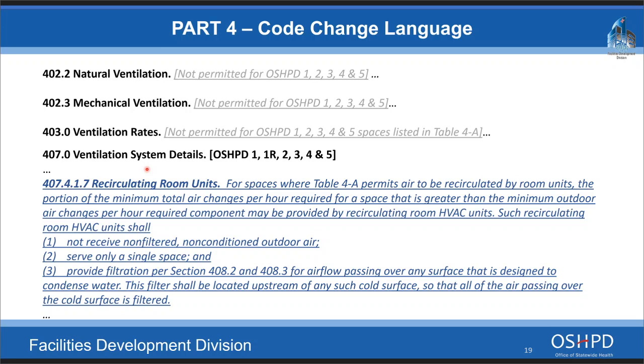Okay. Yeah, there are some areas in model code in 62.1 style ventilation that do not apply to healthcare, and they're basically omitted in ASHRAE 170. So we're trying to show that here. Some of the sections just do not apply. I think 402.3 even says we have occupancy sensor type of requirements and things like that.